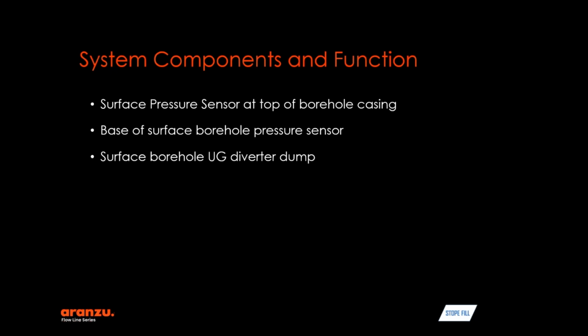So, the diverter at the bottom of the surface borehole is located 20 to 30 meters downstream from the borehole underground breakthrough. This diverter dumps the full pipe cross-sectional flow to a designated sump in the event that a blockage event is detected. This protects the surface borehole and clears the upstream casing, which enables flush water to be applied to the surface to help clear the downstream pipe work, which is particularly important for a pump system that results in a full system of paste material being delivered.